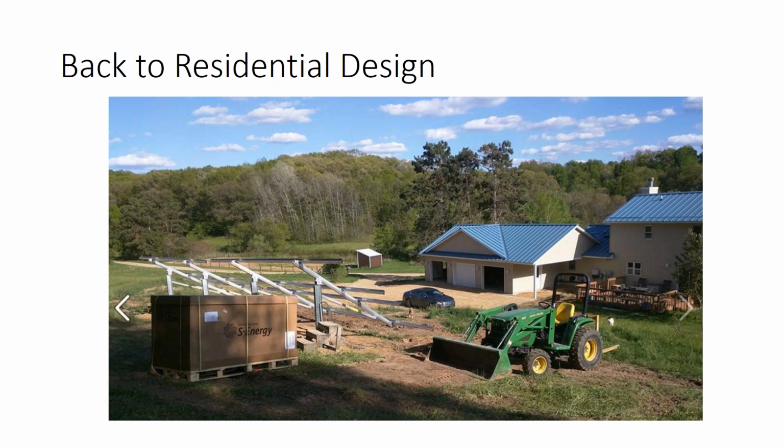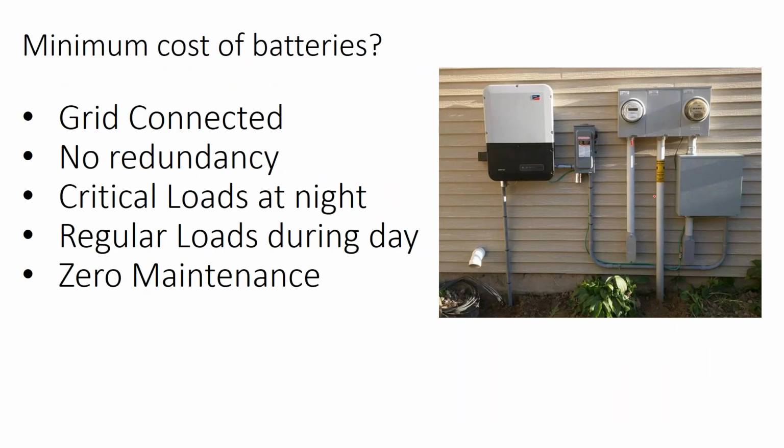So regardless, when you're designing a batteryless solar array, you may want to just go check out the product lines to see if the inverter manufacturer has a roadmap for getting into batteries. Most do, though. So anyway, here's our batteryless inverter system. We had 3 circuits coming from our solar array. We actually went and looked at the home electric bill, and they really needed not a 7 kilowatt solar array to meet their energy needs in an off-grid scenario. They really needed something larger than that.